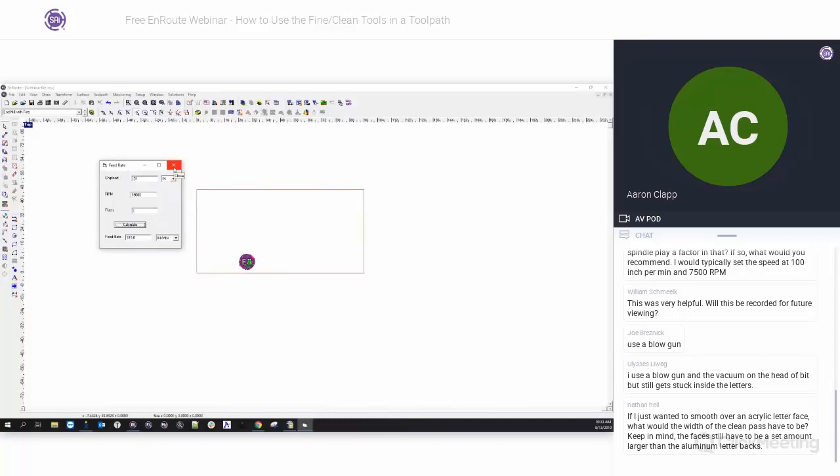But yes, depending on the bit and the spindle speed, you might be going too fast for that bit or for that type of material. You may want the bit, instead of shaving and creating so much dust, to carve out bigger chunks so that it pulls bigger pieces versus just creating sawdust, pretty much. So feed rate and spindle speed could affect that a little bit. So I might check with the bit manufacturer and see if there are some things there that you might want to adjust.